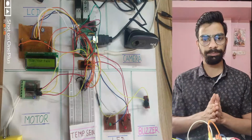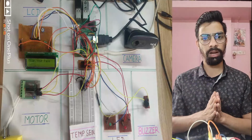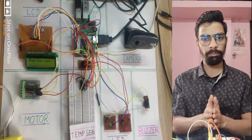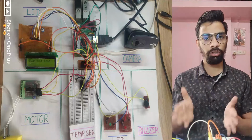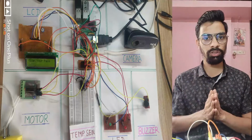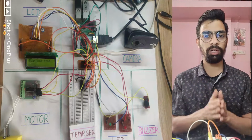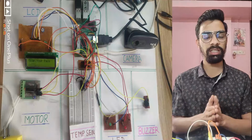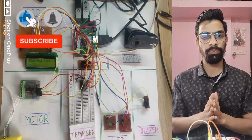The second part is, if the person wears the mask, it will come again in front of the camera, then it will check the body temperature of the person. If the body temperature of the person is greater than 32 degrees Celsius, for this I will use the LM35 sensor for demonstration purposes, then again the buzzer will turn on and the red LED will glow.